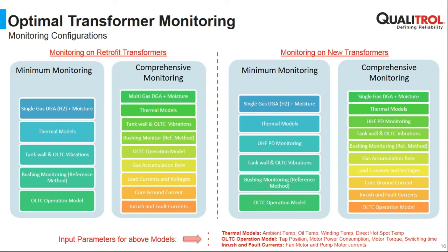From our analysis, yes, these are sufficient provided you are doing the right kind of measurement. And this right kind of measurement is you should be monitoring the absolute power factor and absolute capacitance. It should not be relative power factor and relative capacitance. If you're monitoring relative power factor and relative capacitance, definitely you have to go with the offline testing.